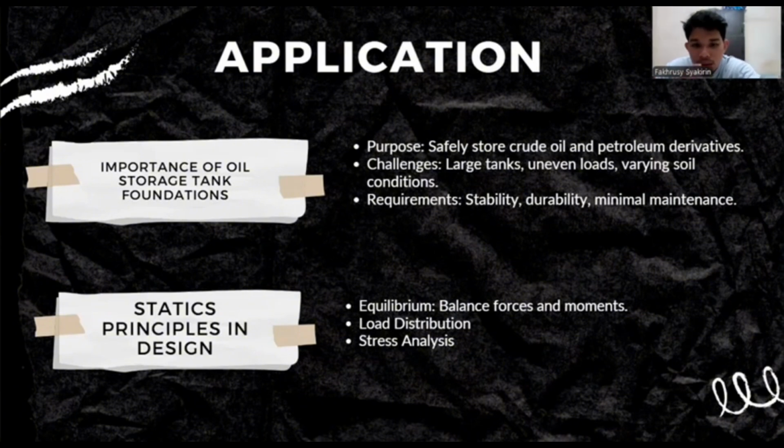Second is static principles in design. The application of static principles in tank foundation design is essential to ensure that forces and moments acting on the structure are in equilibrium. This involves careful analysis of vertical loads, such as the weight of the tank and its contents, as well as lateral forces caused by external factors like wind, seismic activity, or uneven settlement.